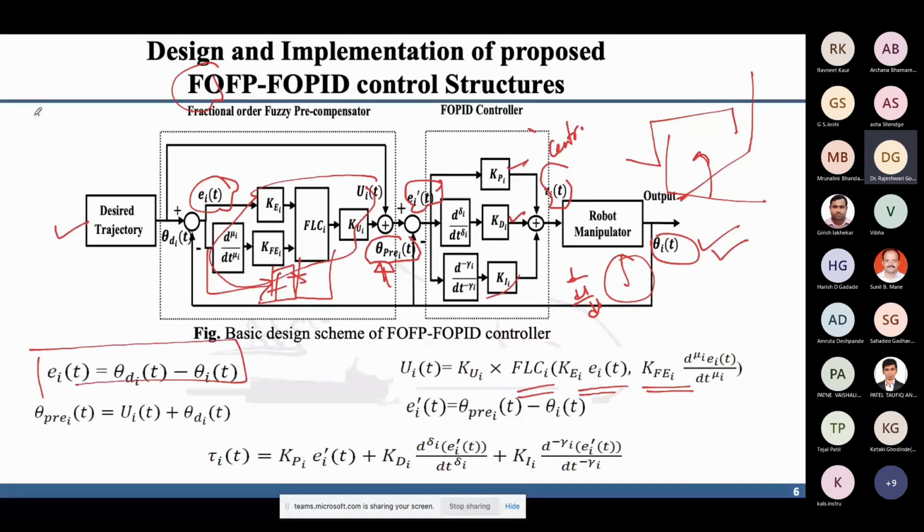Just like we talk about the PID controller: P is just proportional, and D just differentiates whatever input we are getting. But what is the integral's role? If we have a very small error, the integral accumulates it and makes it big. That is why the integral windup concept comes into the picture when we are using three inputs, where the third input is the integral.